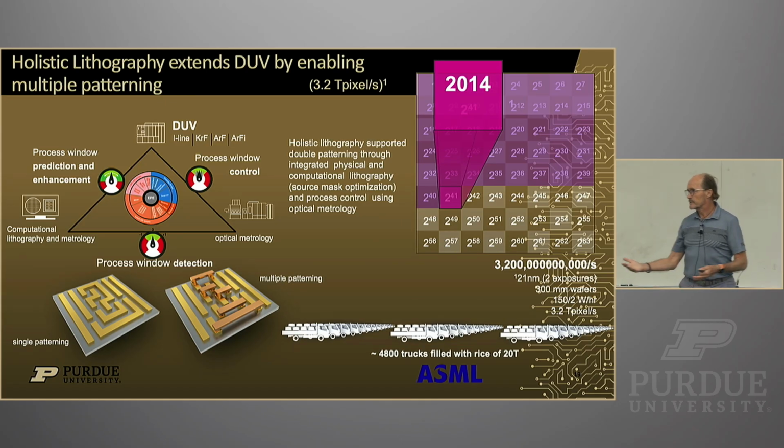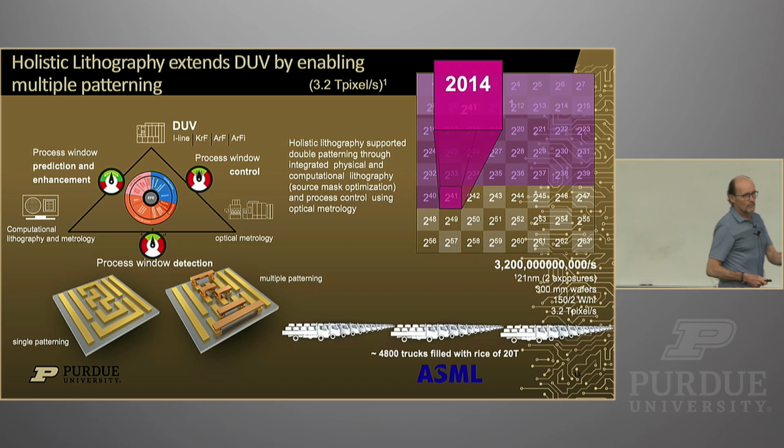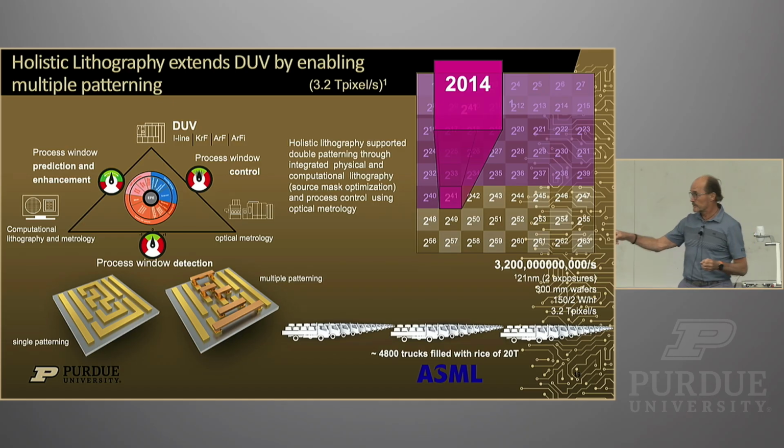Now, I don't have the time to look at 10 million transistors, whether they come out. So how can I select perhaps 10 structures that I can look at in metrology, infer from that what is happening with the 100 million or billion of transistors that are on my chip, and use that inference to say, this adjustment of the knobs makes all of the patterns better. Because that's what customers were very worried about, right? You measure only a few patterns, you want to adjust them so that they're better. Are you going to mess up the rest of my chip?